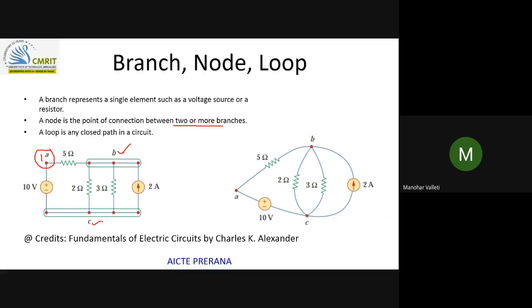So in this circuit, even though 8 nodes were there as per the definition, when we are solving the problems, we will consider only 3 nodes, assuming that all those nodes are at the same potential. See, these all 3 nodes I am considering as one node because all these three are at equipotential only. So if the nodes are at equipotential, we will consider those nodes as one node only. So same way below also. Generally, whatever the node is there below, we will consider it as ground.